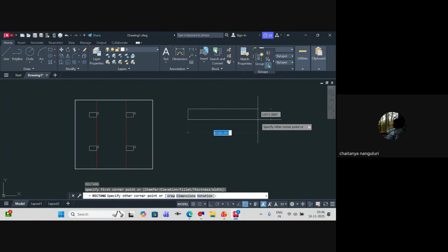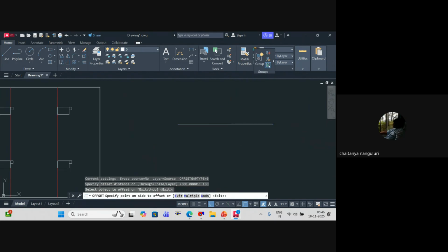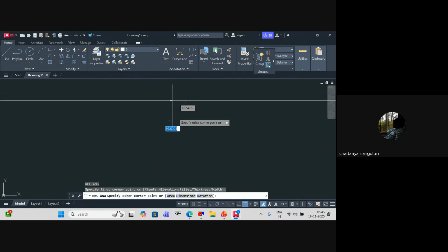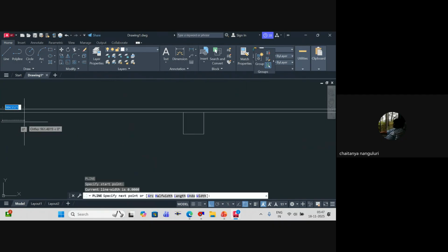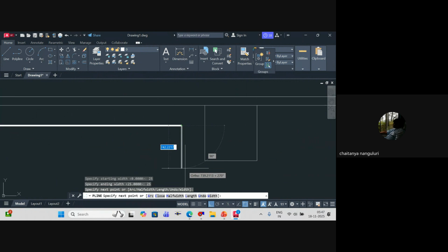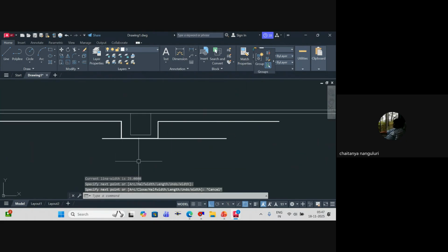Yes, sir. So you will definitely have your beams and columns. Let's say this is your beam and this is your column. This beam is, let's say, 600 or something. Then whenever you have a water curtain pipe, your water curtain pipe should bend like this and then it should go back to the slab. It should never be just in this direction because you'll have a lot of space in that case. It's better to avoid that as much as possible. Understood? When you install a water curtain, you have to carry it near to your slab always. Please remember that.